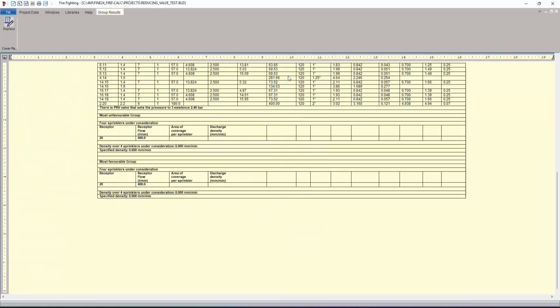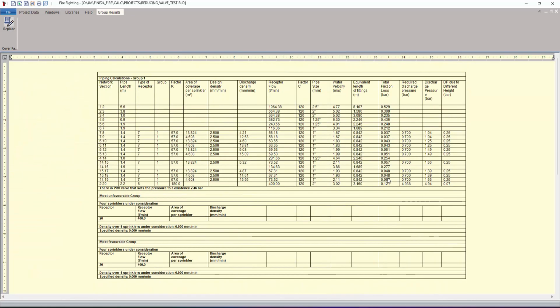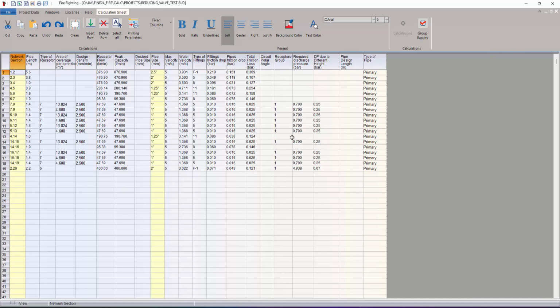As in the previous procedure, we expect a decrease in friction losses following this approach, and therefore a reduction in the required pressure at point 3. We will again perform iterative steps until we achieve the desired result.